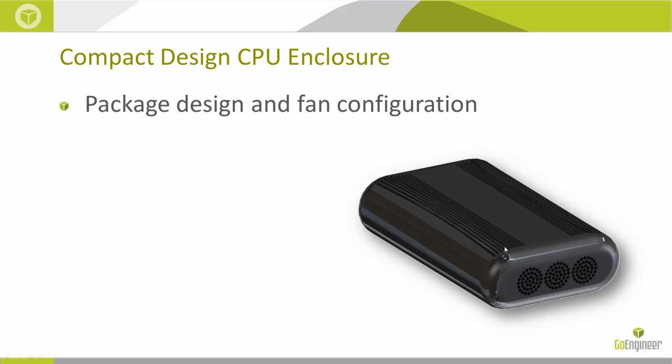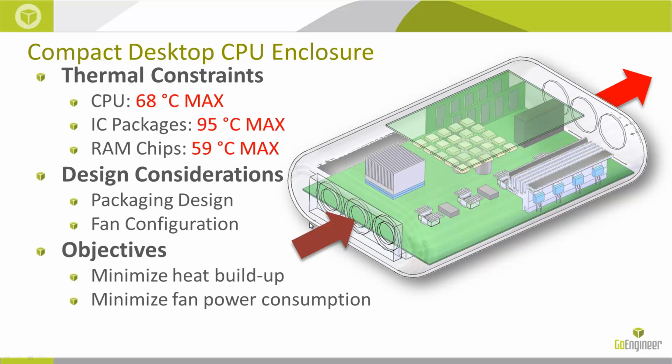We want to look at whether the vents being in the model or not gives us the best cooling of our electronic components. We have an outlet here and the fans are on the other side. We want to try one with the vents, one without the vents, and one with 1, 2, or 3 fans, and see which one gives us the best properties. Oftentimes you might even be surprised with what gives us the best results.